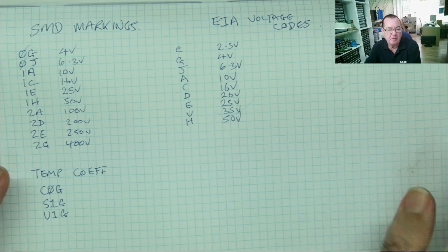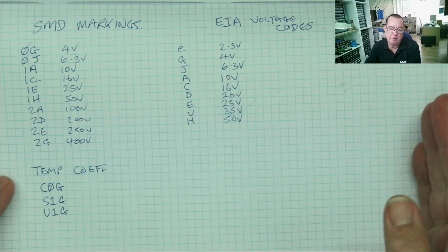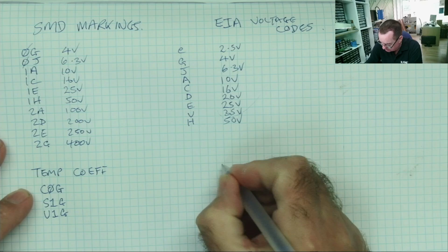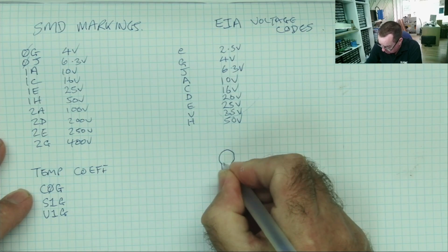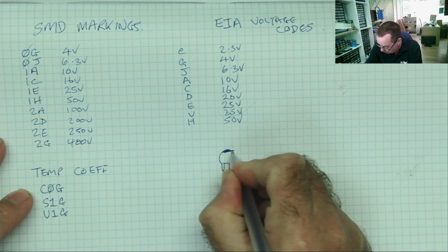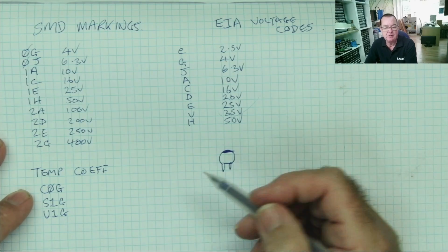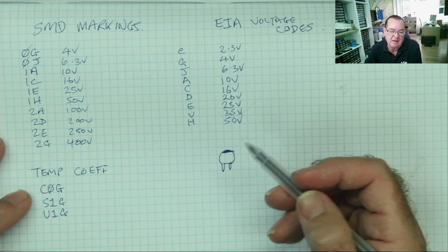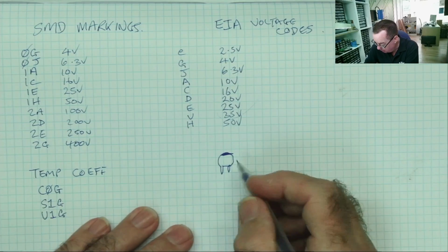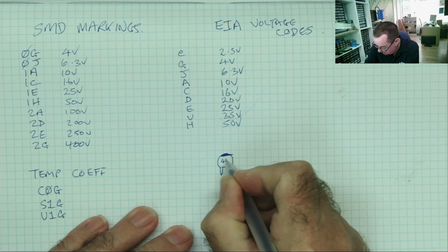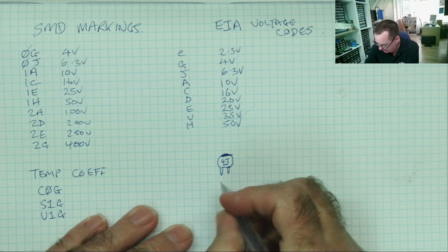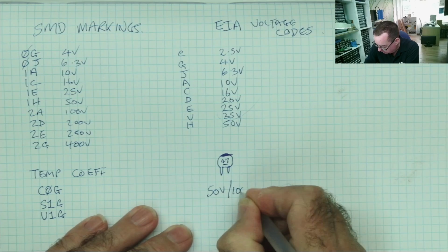I'll just add to this video here, guys. After I recorded it and I published part 1, I became more interested in these underlines on these ceramic disc capacitors and what they actually meant. So I had another go at Googling it, and this time I actually found something useful, I think. So we know the black or the coloured tip is temperature coefficient, and there are colours other than black, although the ones I have all seem to be black. And I found out 2 interesting things. One is this underline. If the value has an underline, that capacitor is a 50 or 100 volt capacitor.